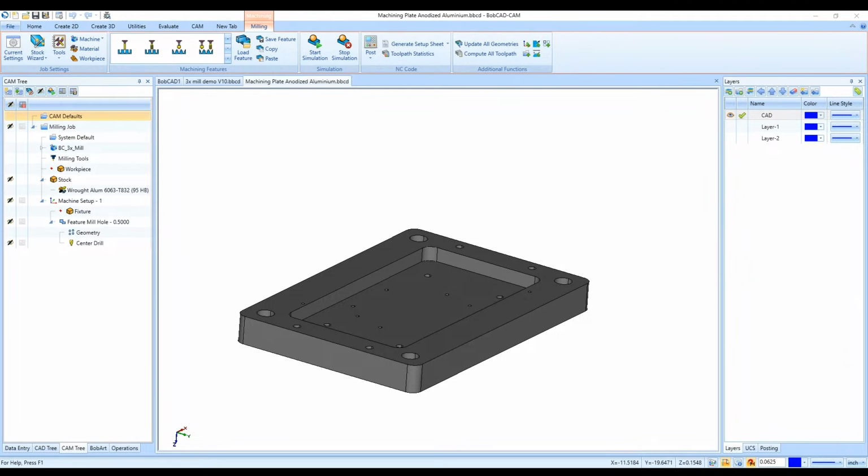So today we'll be looking at the advanced drilling options that we have now. We now have a hole recognition option to be able to define a solid model in our CAM system and let the CAM system do the work for us to recognize all of the different hole sizes that we've got with this part file here and sort all of the operations out by hole size. Let the software know if we're going to be doing a tapping operation or counterbore operation along with it, and also if there's a chamfer among the holes, if we're going to be doing the chamfering as well.